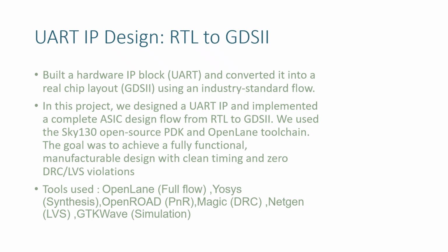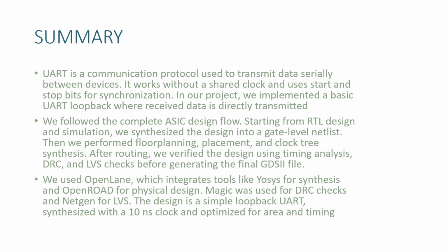The second project was UART IP design from RTL to GDS. In this project, I designed the UART IP and implemented a complete ASIC design flow from RTL to GDS using SkyWater 130 PDK and OpenLane toolchain. The tools used for this were OpenLane, OpenROAD, Magic, Netgen, and GTKWave.